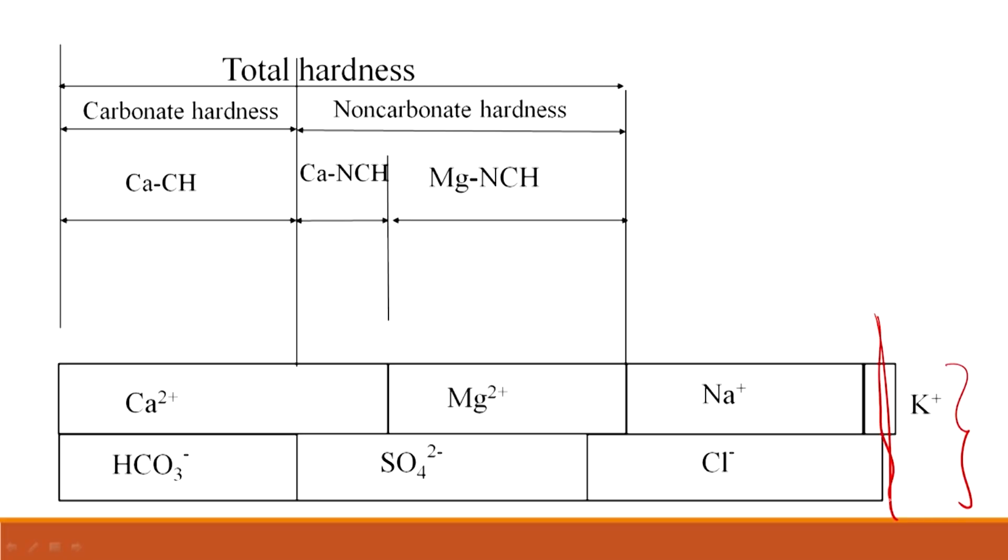And then what is total hardness? As we know, it is the one associated with calcium and magnesium concentration. So, that is why we see this as total hardness, right. And then for HCO3 minus, because pH is 7.2, will there be any CO3 2 minus? Not really, right.